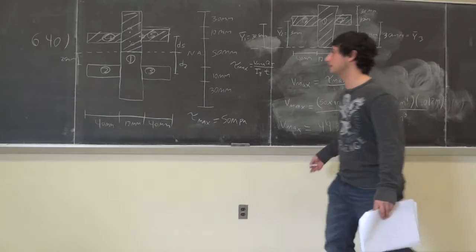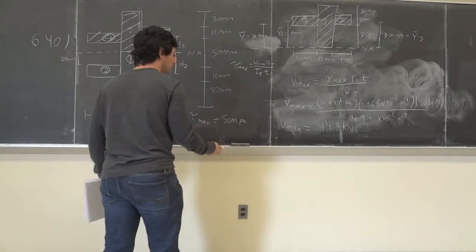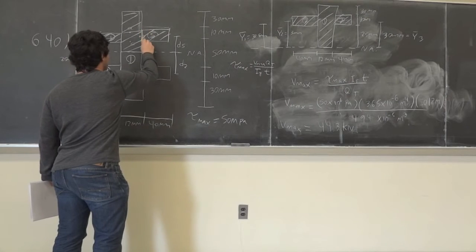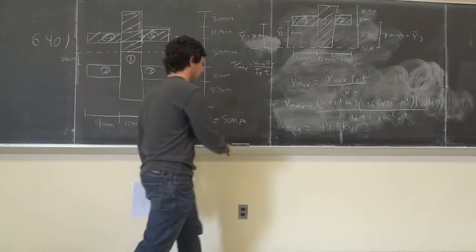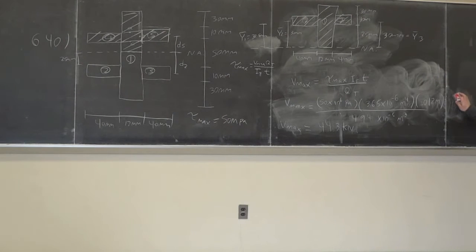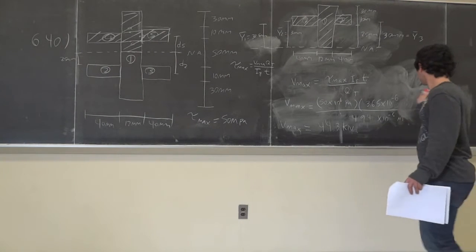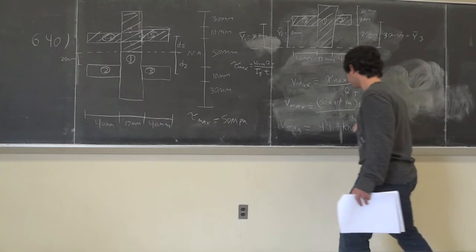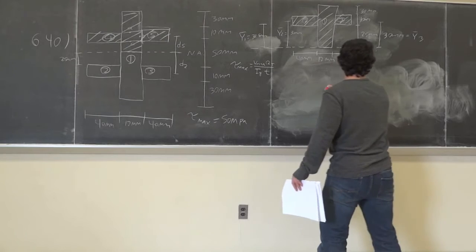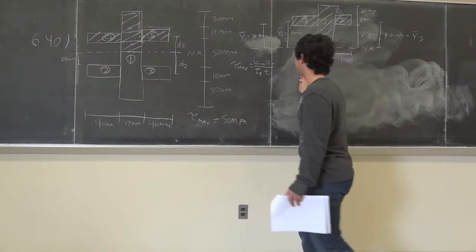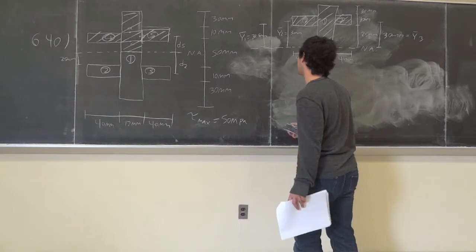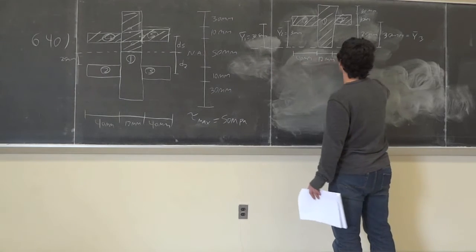Once you solve for this, now we know the maximum shear force. You're going to need that to find the transverse shear in this section, and this section. You guys got it. So now that we have that, that's good. So now let's start with section A. We want to do transverse shear in section A.